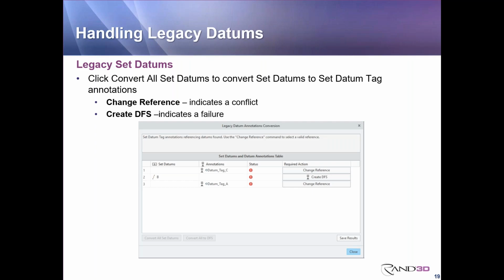You can hover your mouse cursor over the symbol in Creo to display additional information that is related to the conflict. And with the later versions of the software, the descriptions are usually worded in such a way for you to understand the issue.